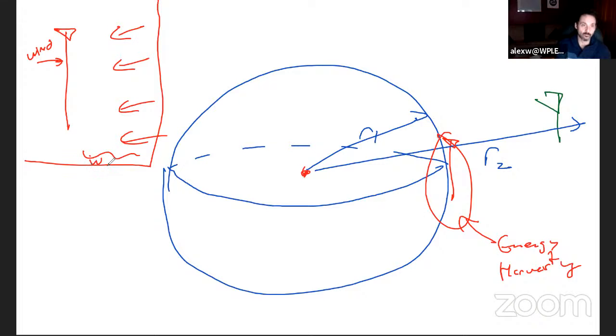So if you have a piece of metal that's lambda over 2, it is great, because remember, we deal with sinusoids and cosinusoids. Half a wavelength is half a period of the sine or cosine wave, not a symbol period. Very important. This is not T_S.